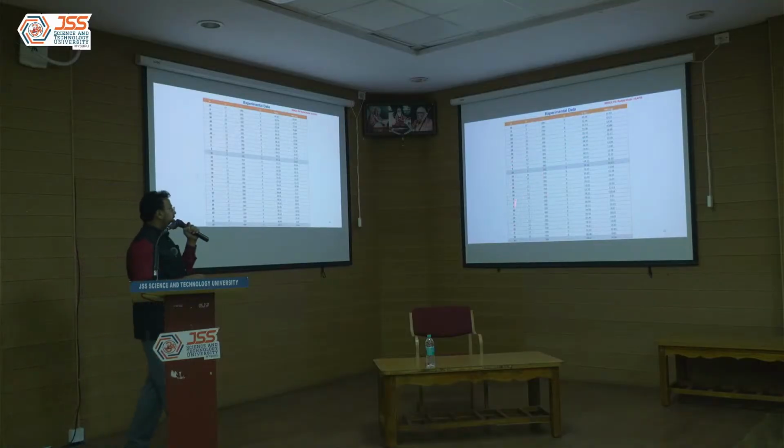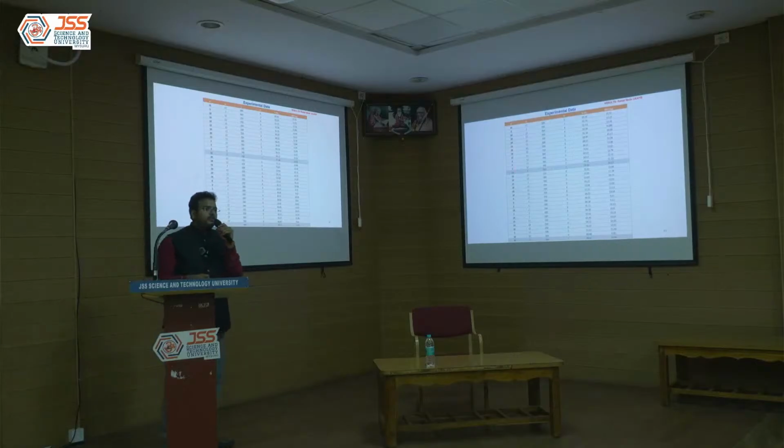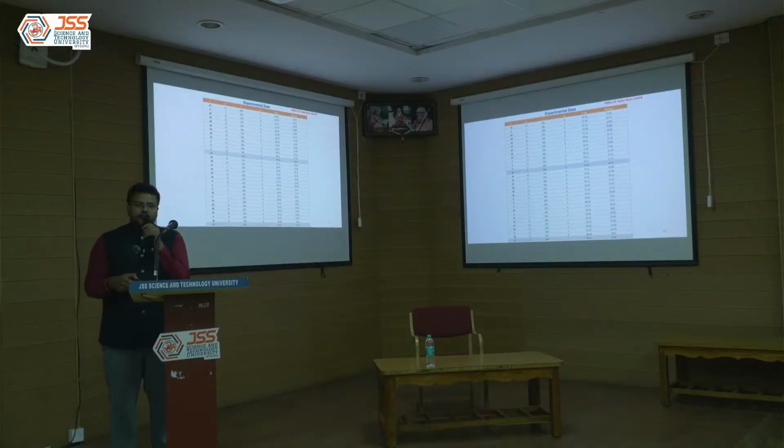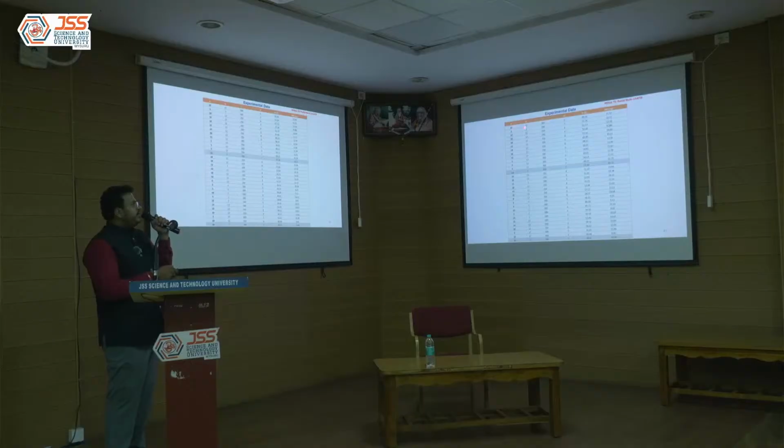31 experiments were conducted using response surface methodology while using ultrasonic assisted abrasive flow machining. So we have coded parameters like A, B, C, and D. Coded parameters means A is my applied frequency, B is extrusion pressure, C is mesh size, and D is the processing time. And we have recorded for the 31 experiments, we chose 5 levels, 4 parameters using response surface methodology.